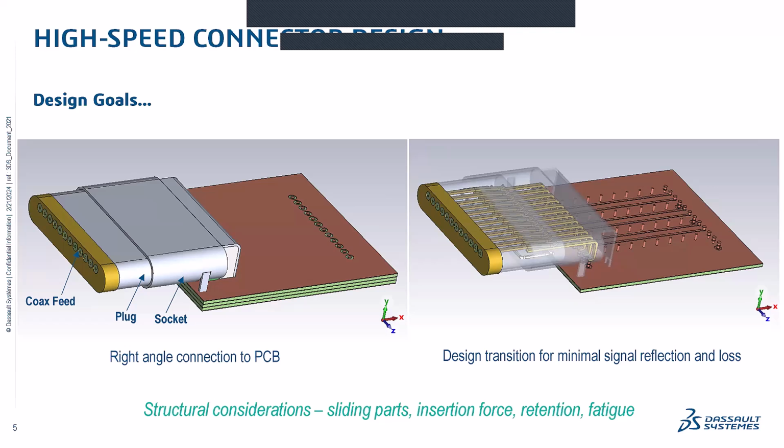These are two parts that are going to be pushed together, and it needs to be robust mechanically and, of course, perform well electrically. The pins have to make contact correctly in order to minimize signal reflection and loss, because that would cause signal integrity problems. But the springs also need to hold the connector in place with the correct force so that it doesn't come out accidentally, but it can still be inserted and removed relatively easily by the user.